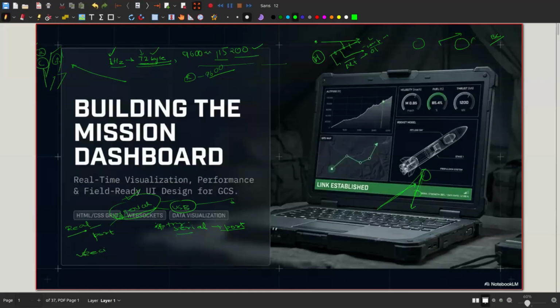Just go to the hardware settings and search for COM ports. You will see there are multiple available USB ports. As soon as you connect your microcontroller, you will see that, okay, COM11 is connected. So there will be an option such as COM11, and you get that this is your port. This is the port number that your laptop recognizes whenever it connects to a microcontroller which has a USB. So basically the Python library in the backend tries to look out for the ports.